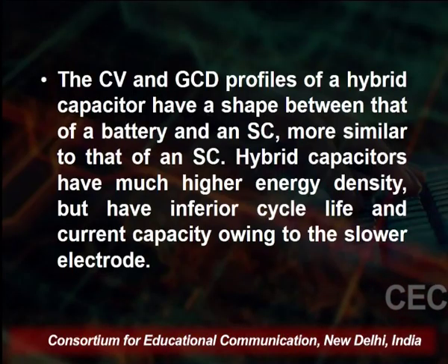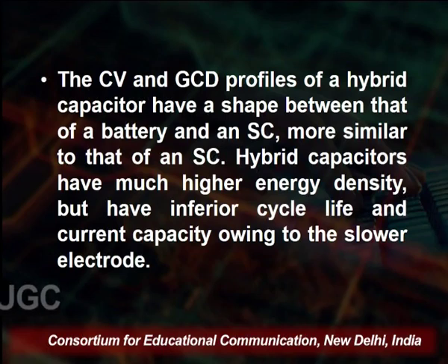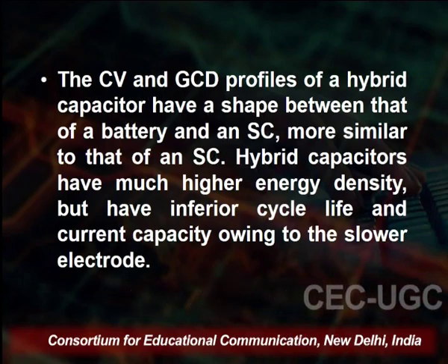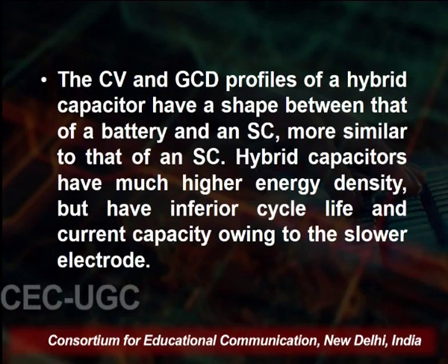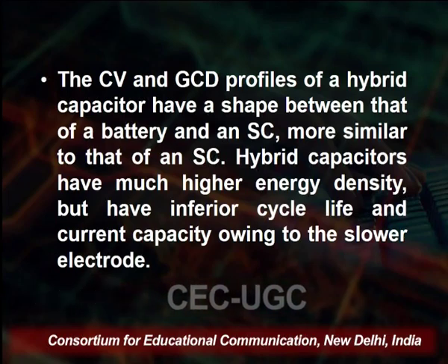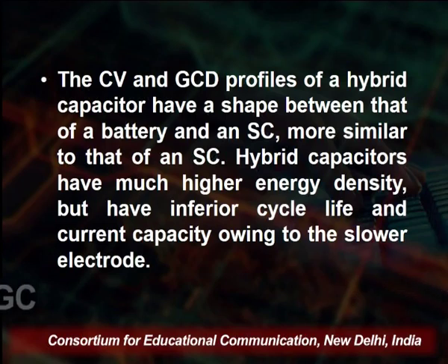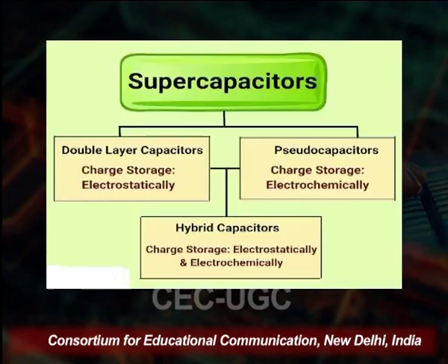The CV and GCD curves of a hybrid capacitor have a shape between that of the battery and the SC, more similar to the SC. The hybrid capacitors have higher energy density but have inferior cycle life and current capacity owing to the slower electrode.